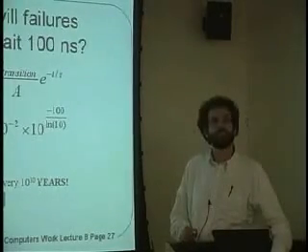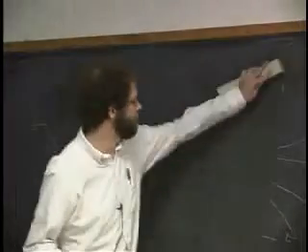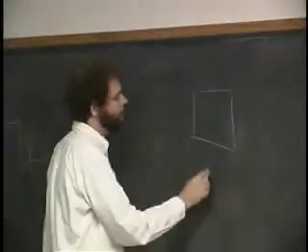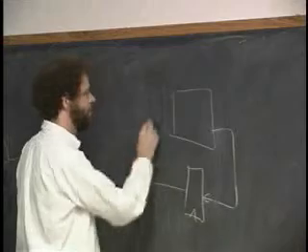The important thing is you can't run this on every flip flop, right? So there's still the question of you have to determine whether or not it's an asynchronous input, determine whether or not you put it into this. Since it's not in the lecture, let me skip to a future lecture and tell you how we're going to solve the problem of how to synchronize these things. You don't want to do it on every one. This is actually in a later lecture, but let's talk about it now, okay?